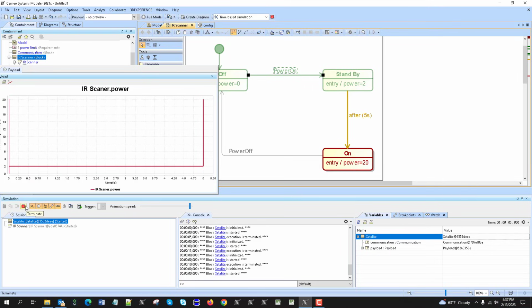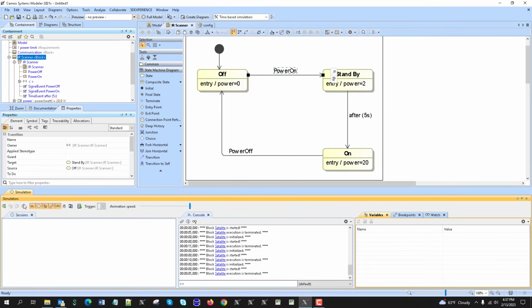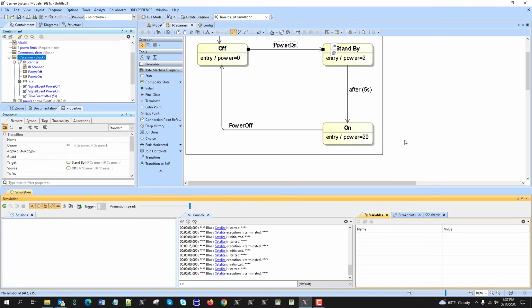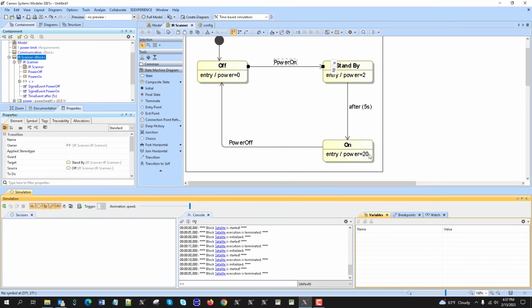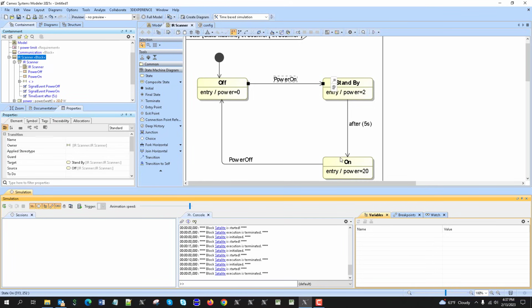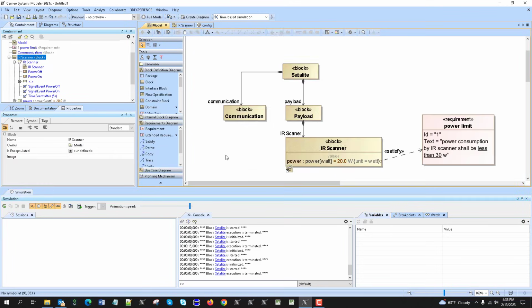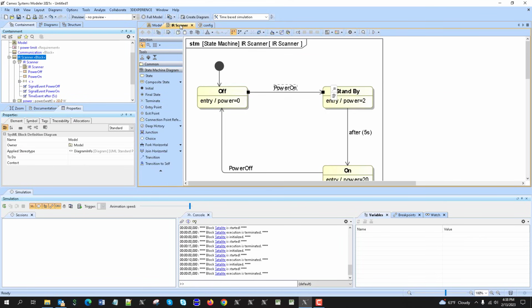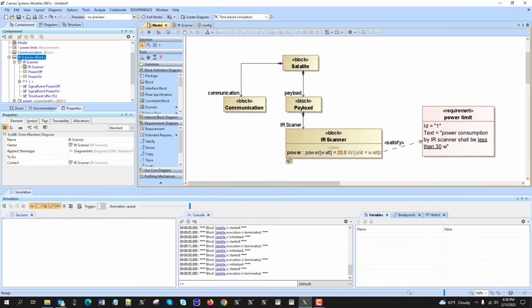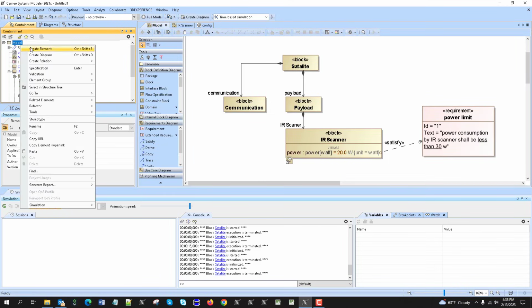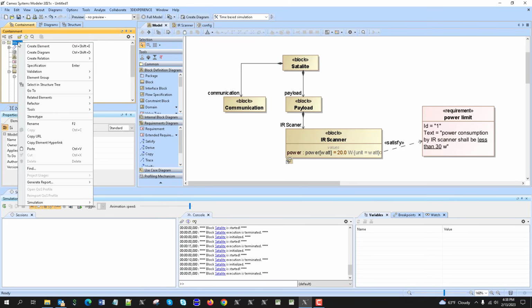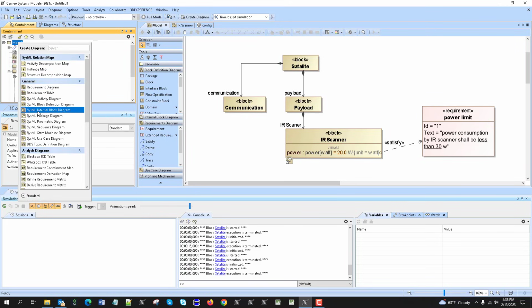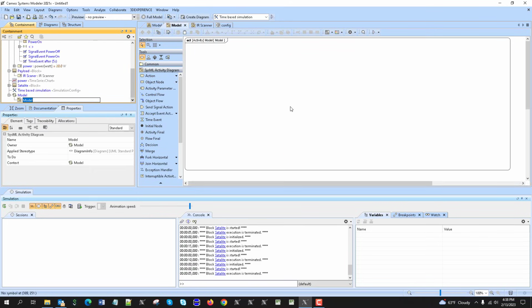but get actual results. Now, what else we can do, we can actually execute the activities which would run and modify those properties. Those activities can be executed directly by the state machine. So let's do it, right? Let's say, do the monitoring. Let's do the activity. That activity can be created anywhere, right? Right click, create diagram, SysML activity diagram.